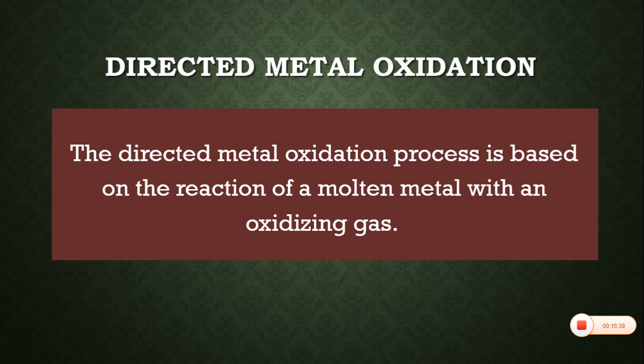But this novel directed oxidation method, in which a molten metal reacts with a gas, has been developed especially for the production of porous and dense materials, as well as composites. The directed metal oxidation method is based on the reaction of molten metal with an oxidizing gas, a liquid and a gas phase.